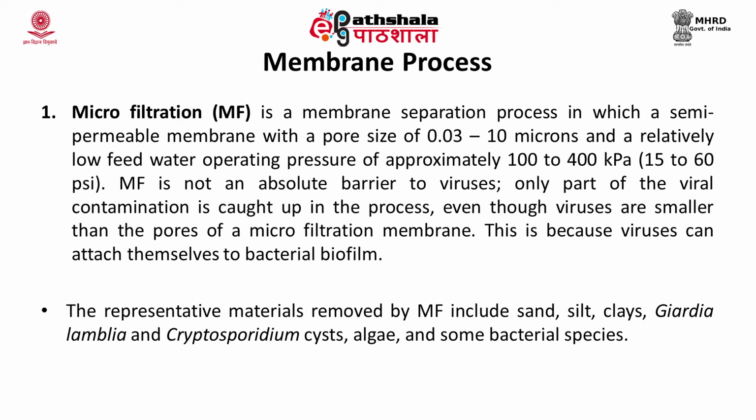Microfiltration. Microfiltration is a membrane separation where the pore size of the membrane ranges between 0.03 to 10 microns and the operating pressure is 100 to 400 kilopascal. Representative materials which are removed in the microfiltration process include sand, silt, clay, giardia and cryptosporidium cysts, algae and some of the bacterial species. As microfiltration is not an absolute barrier to the viruses, only part of the viral contamination is caught